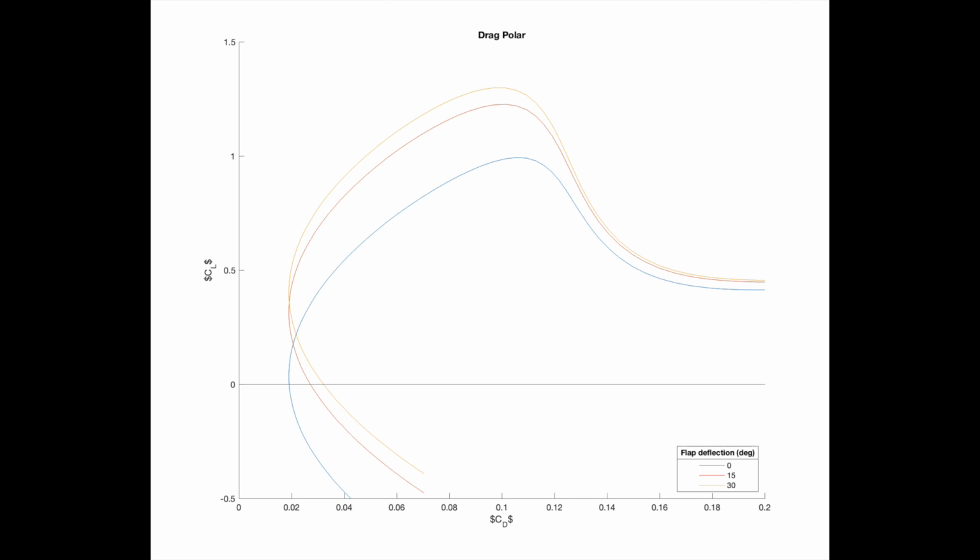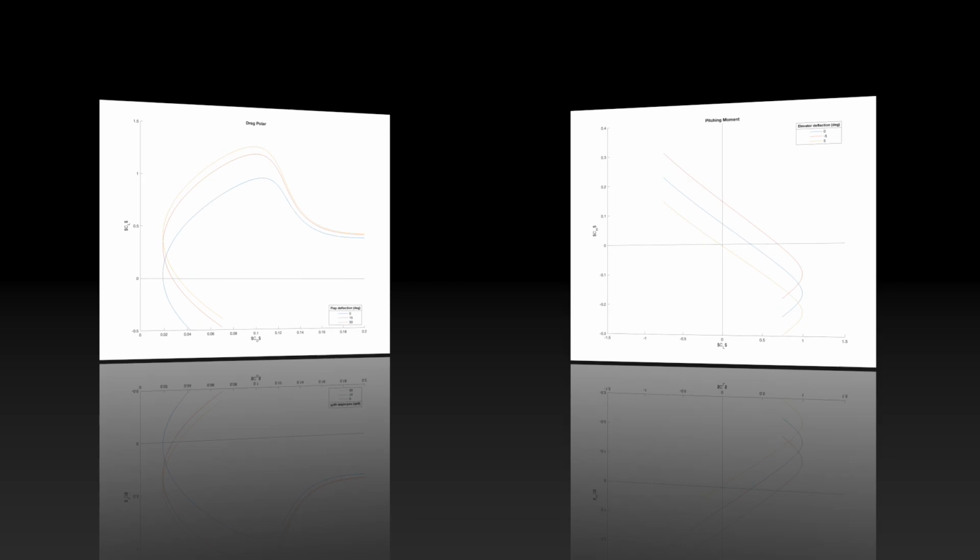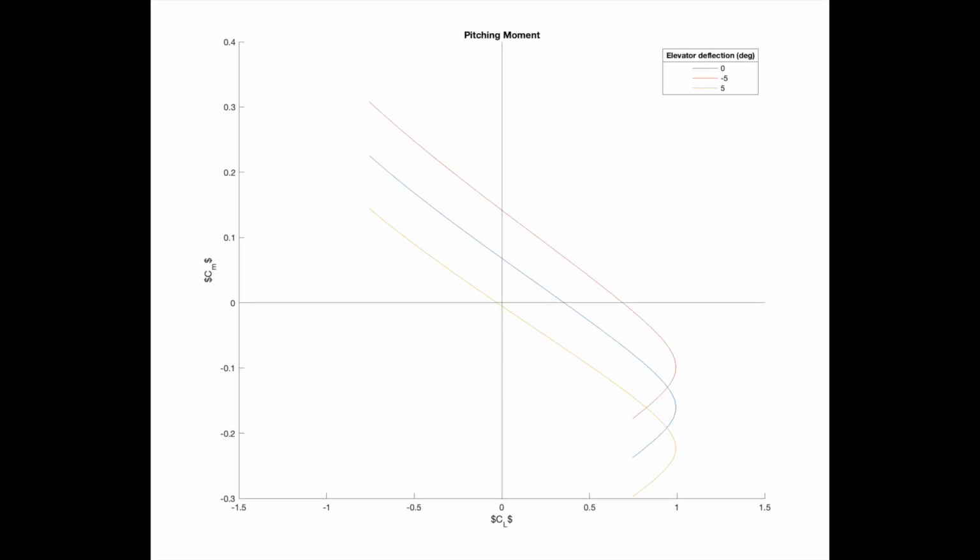For this, several elevator angles are presented together with the coefficient of moment at the center of mass versus the coefficient of lift for the default COM position of 0.058 meters from the leading edge. The plot makes clear that the curve with a 5-degree elevator deflection goes through the origin. This implies that the best performance is guaranteed by an elevator angle of 5 degrees to trim.